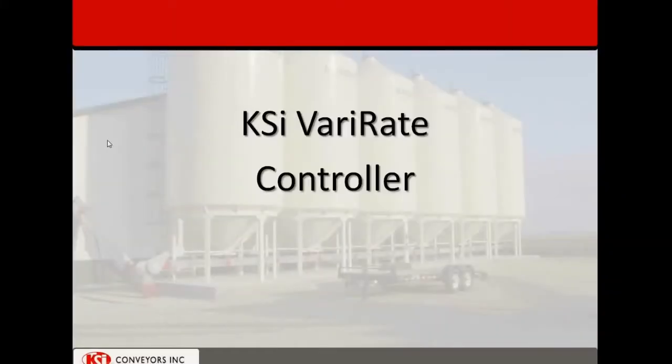Okay, the KSi VariRate controller is a control system that is designed to allow you to deliver a specific rate of seed through your treating device, and also to give a signal to the pumps, the liquid pumps, to tell them when to turn on and when to turn off based on when there is or is not seed flow going through the treater. The VariRate controller can be put on any existing or new treating system that does not already have a seed flow device.